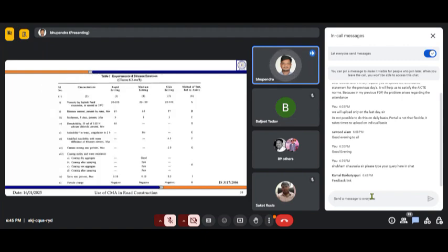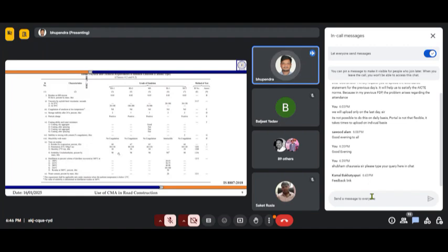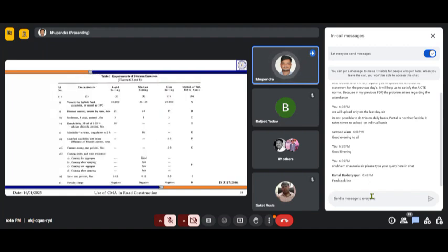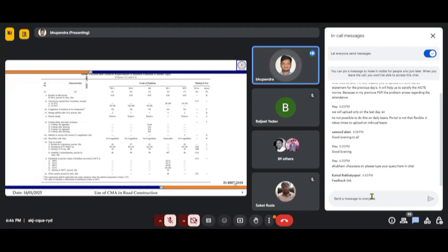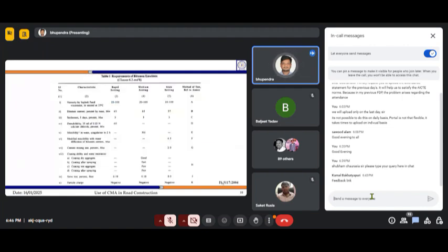Now similar requirements are given in IS 3117, which is for the anionic type of emulsion. So here you can see the particle charge is negative, and all the different tests which we have already discussed in the previous slides are there. So I am not going into the detail. There are two different codes: for the cationic type of emulsion, it is IS 8887, and for the anionic type of emulsion, it is IS 3117. Okay, so that can be used to categorize and to check the characteristics of the bitumen emulsion.